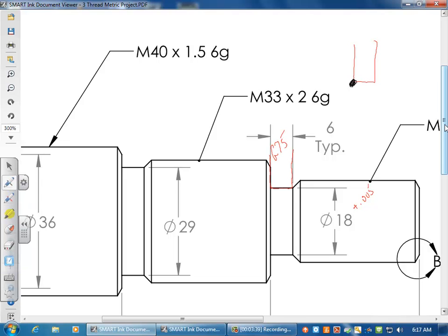And then with your G70, or with the G01s, basically what you're going to do is come down to this point. You have to remember to take into account the width of your tool. Then you're going to put in your 45. Then you'll be here, taking into account your tool, G01, G01, and then wrap it back to your next one. So that little bit of a chamfer you can just take in one pass. Like I said, you want to stop off your part, feed down to this point, down to here, and then finish that groove. All the while, keep in mind that this is the corner of the tool that you're using. So that would take care of your grooves.